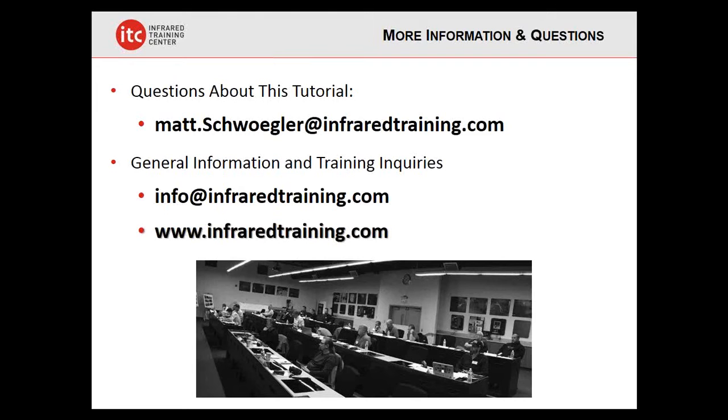No. Okay. Let's see. They're kind of flying in here now. In the example for a light bulb in the box, the emissivity didn't change between looking at the outside of the box versus the light bulb on the inside. Should the emissivity be adjusted based on the material being inspected? The short answer to that question is absolutely yes. If you're measuring temperature, or what we would call quantitative thermography, emissivity always needs to be set properly.